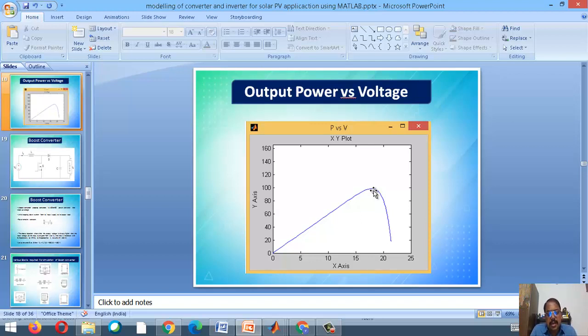Now the output of the solar panel will not be the required voltage; it will be around 92 to 96 or 98 volts. From there I want to convert it into the required voltage. For us, the AC unit is 230 RMS, but the peak is 230 into root 2, which is nothing but 326 volts. So how do we get this 326 volts from the output of the solar panel?